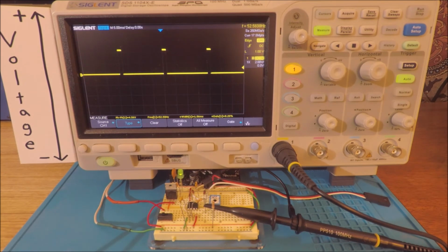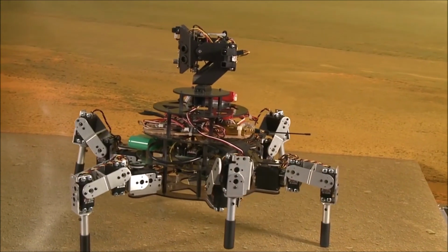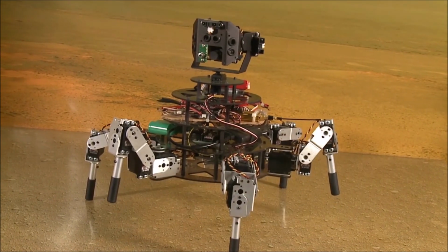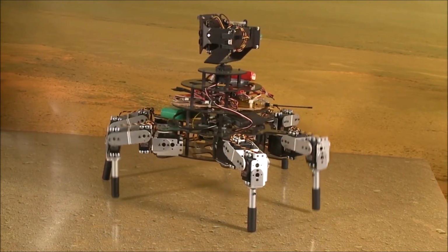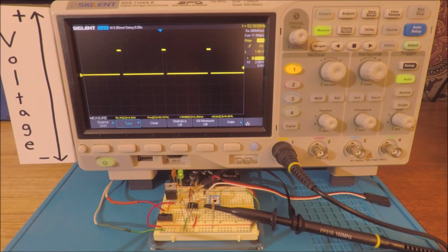The significance of this 50 hertz PWM signal is this happens to be the protocol that you would use to command a servo drive, the type of servo drive for moving around a robot or controlling one of the flight surfaces on a drone. Servo drives are angular position controlled devices.